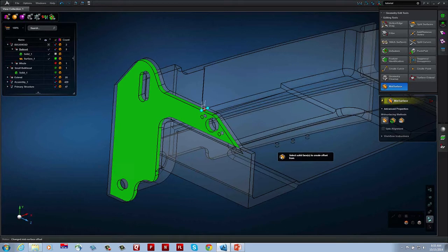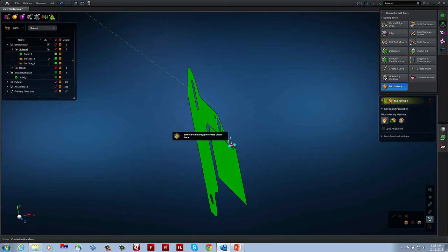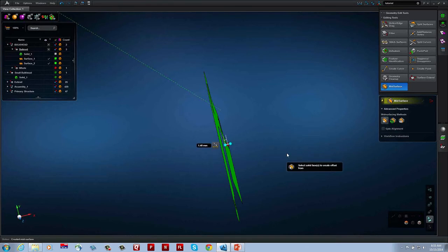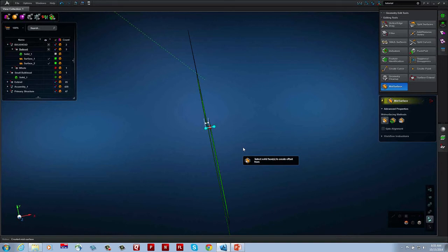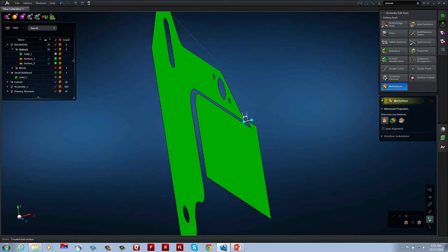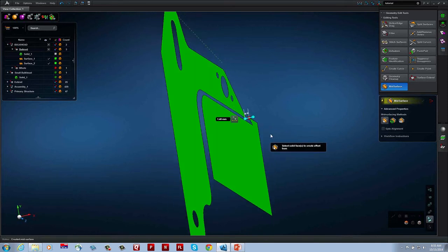So that's my first surface. I'm going to do a second surface. When I do this second surface, because there's different thicknesses and different offsets, these two guys actually don't show up on a common plane. Now, I know there's many. If I give a mid-surface model to 10 different people, I'm probably going to get 10 different representations. So I know a lot of people would want to keep this step in there. For my purposes, though, I actually want to eliminate that.